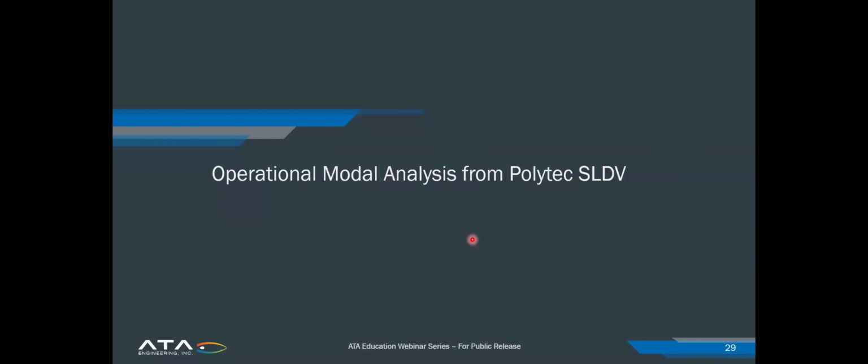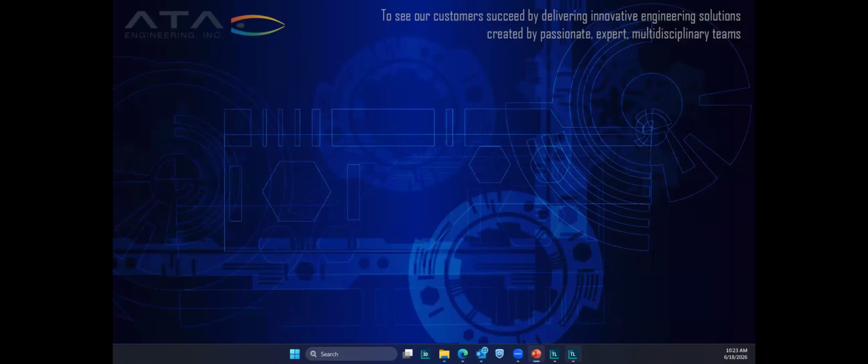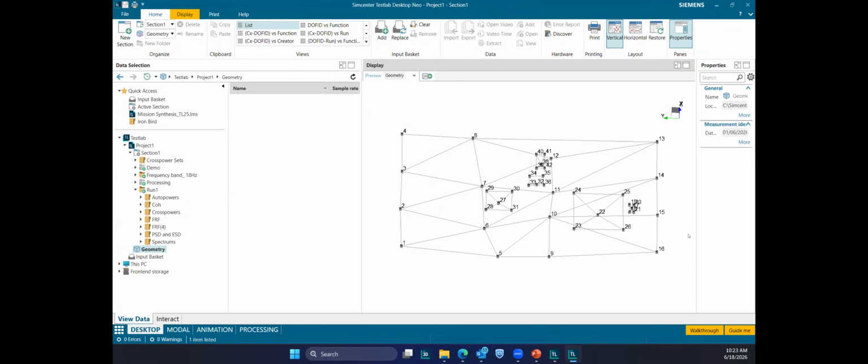And so what I wanted to do is take the data off that vibrometer and show you how we can do some operational modal analysis from that SLDV data. So I'm going to stop sharing that. What we can do is, right here, I just exported the data from the laser vibrometer, and this is what we have. We have all of our scanning points shown right here.